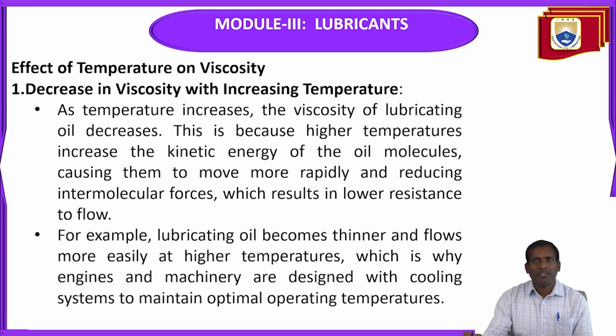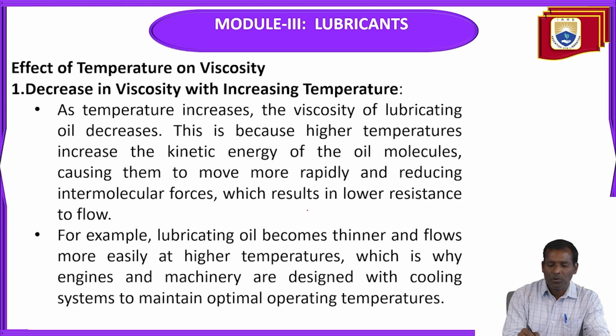As temperature increases, the viscosity of lubricating oil decreases. This is because high temperatures increase the kinetic energy of the oil molecules, causing them to move more rapidly and reducing intermolecular forces, which results in lower resistance to flow.